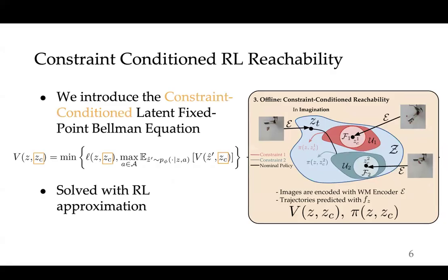Next, we have reachability. Reachability is the fundamental backbone behind our project. It allows us to compute what we call an unsafe set. We have this fail set where anything inside it is determined to be failure. But the unsafe set is the region where if you enter it, you're doomed to fail no matter what you do, right? These might be situations where you haven't fallen over yet, but you're definitely going to fall over.